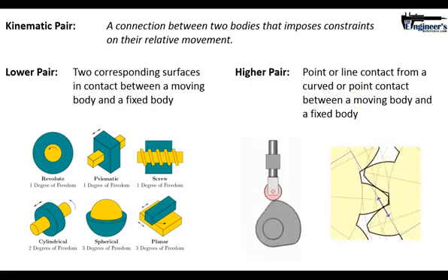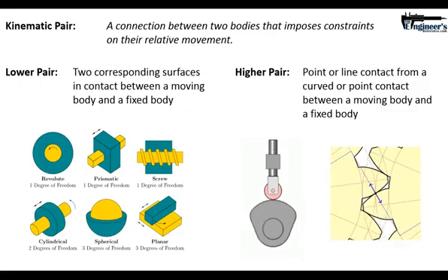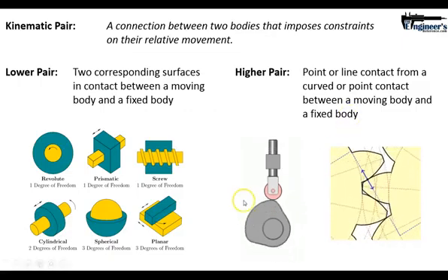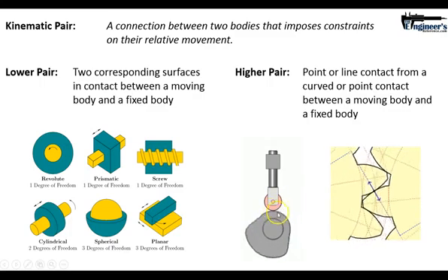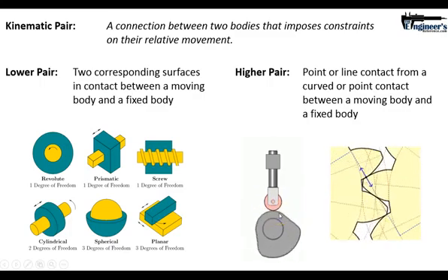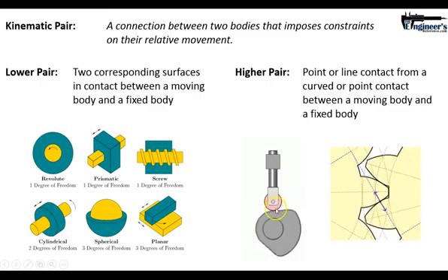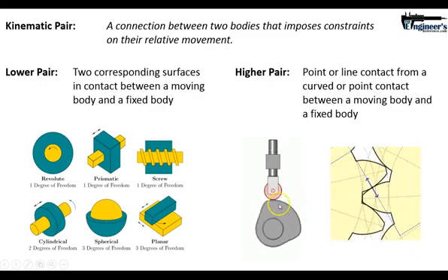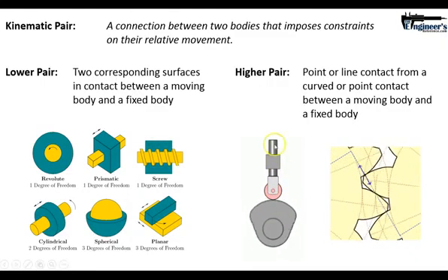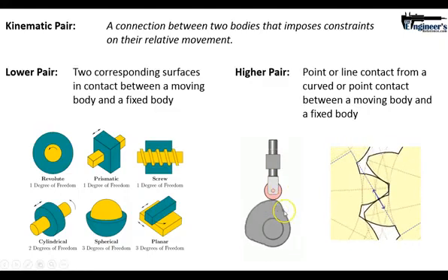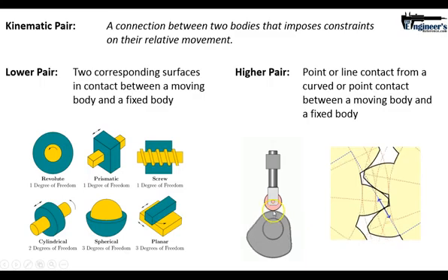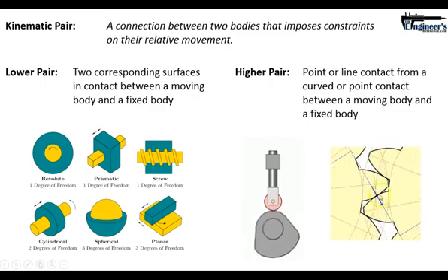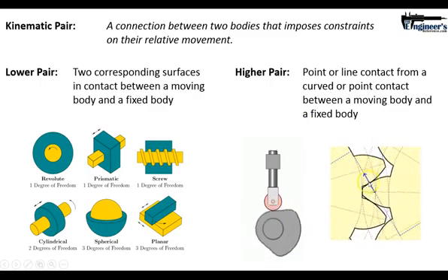So what does that sound like, these curved point contacts? Well, two things. One is cams. Cams have curves as well as point contacts. A curve to curve is a point contact that controls the movement of two bodies. Whenever you see a cam in this particular instance, you're seeing a linear movement going up and down in a very controlled fashion, dictated by what you designed into this cam. Another good example would be the involutes in a gearing system.